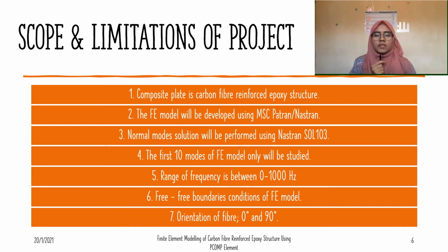Fourth, the first 10 modes only will be studied. Fifth, the range of the frequency is between 0 to 1000 Hz. Sixth, the FE model is free boundary condition. And seventh, the orientation of fiber is 0 degree and 90 degree.